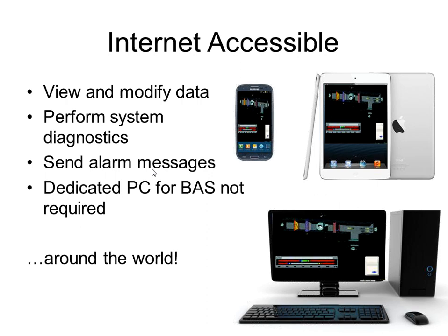General control systems for VVT. VVT is generally DDC based, and with most DDC systems nowadays, they are internet accessible. So you're able to view and modify data, send email alarms, perform diagnostics, and you don't require dedicated PCs anymore where you just have one PC for the whole system.